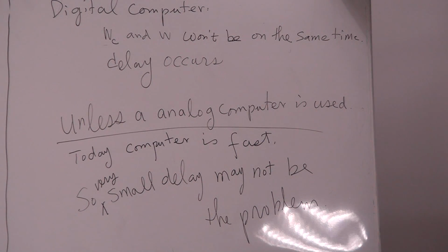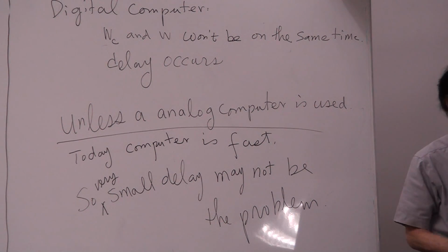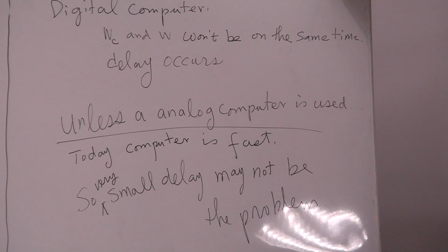So the computer will be busier, rather than just applying the gain and that's it. The computer here has to integrate this differential equation to get WC, so that my U will become minus KC times W minus WC. And this overall system, assuming your power is not cutting off, is a mimic of this controller, this PMP.